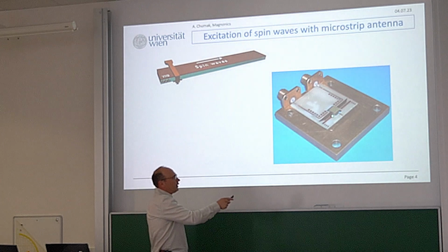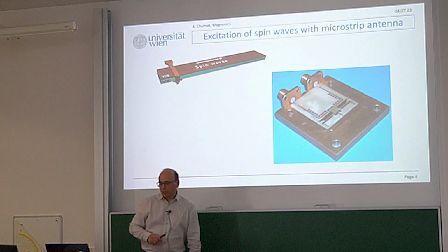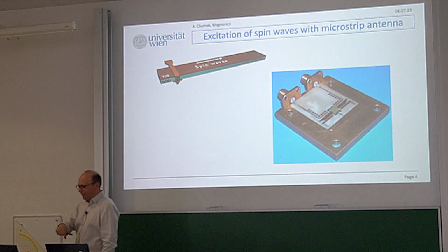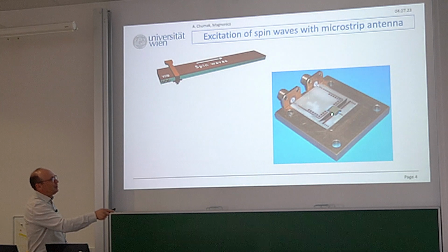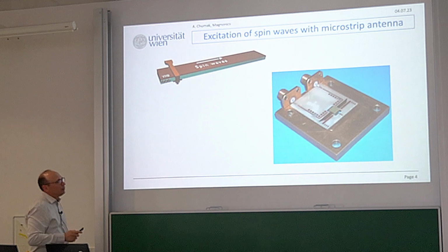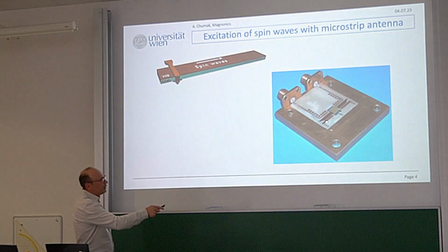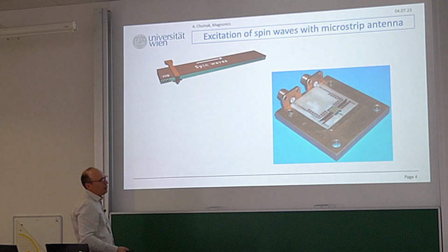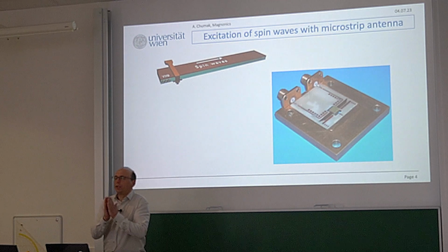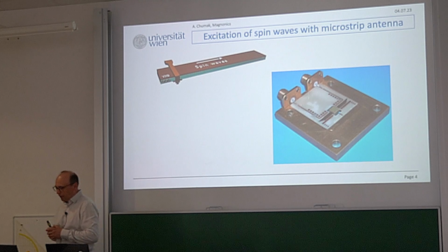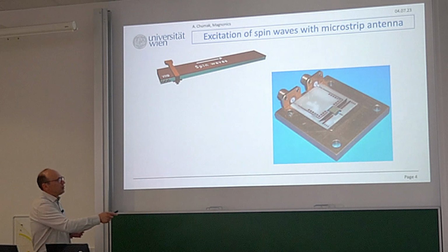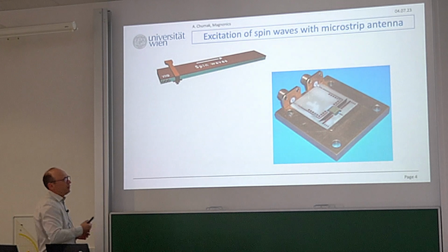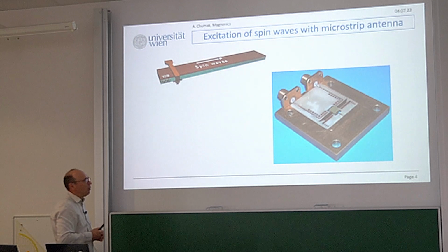It's either a mechanical, real short via, just a tube going down to ground. Another way is to use a big area like shown here. It's more or less a capacitor, which works as a short for the microwave signal. In principle, both work well. Maybe for lower frequencies the capacitor will start working worse.